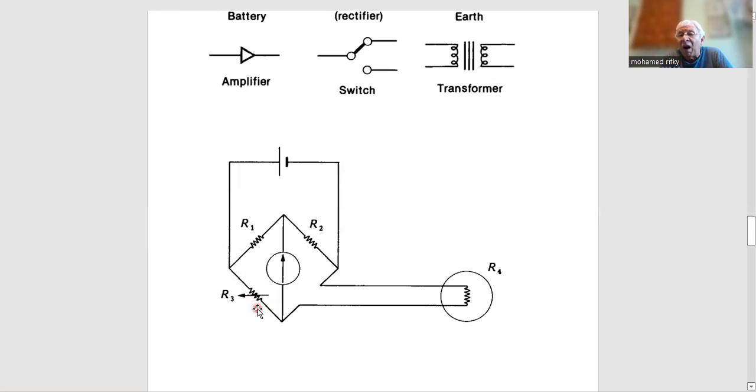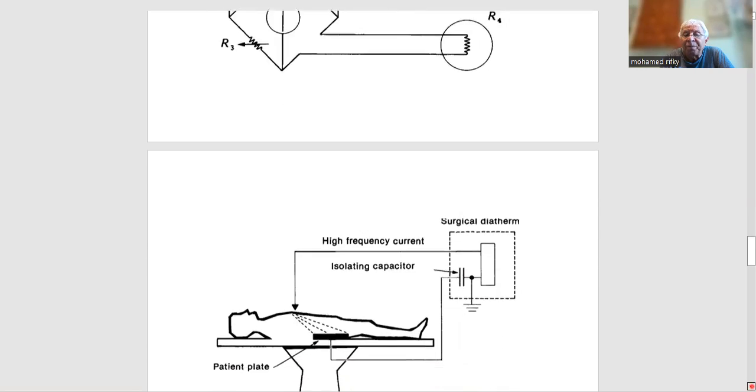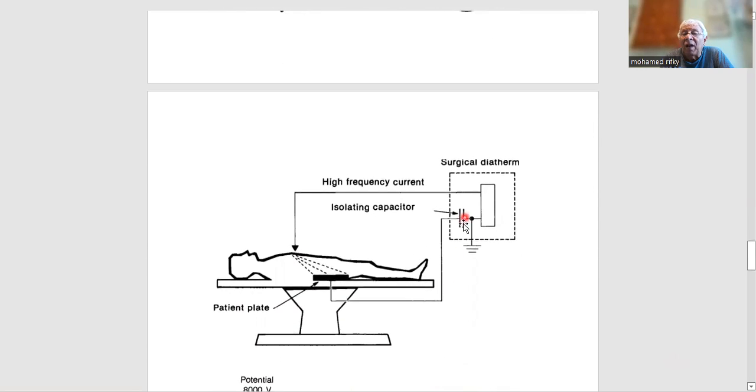I put it in this arm, and then this changeable resistor, which we call a rheostat, is changeable. So whenever I put this resistor in this circuit, this null deflection will be affected. So I come to this R4, I change it till the pointer goes back to 0. This difference can calculate, of course, the unknown resistance, which is R3.